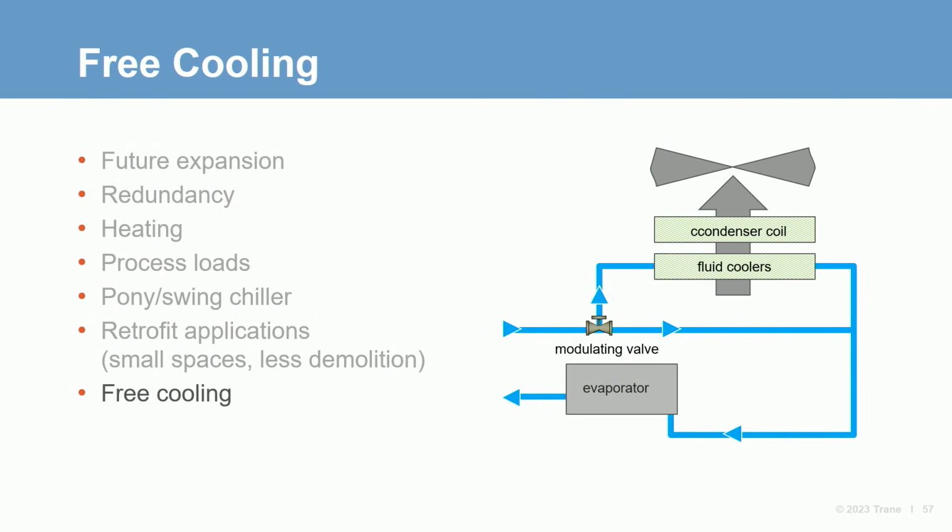Another feature typically seen in packaged chillers is relevant to modular chillers. Air-cooled modular chillers are available with hydronic free cooling coils, aka a water-side economizer. The fluid is routed into coils nested with the condenser coils to be cooled rather than running the compressor when conditions are favorable. A free cooling only module can be included in a chiller bank, acting as a fluid cooler on its own. When connected as the first in the bank, integrated operation is doable too, cooling the fluid as far as it can. The remaining modules can pick up the rest of the load.